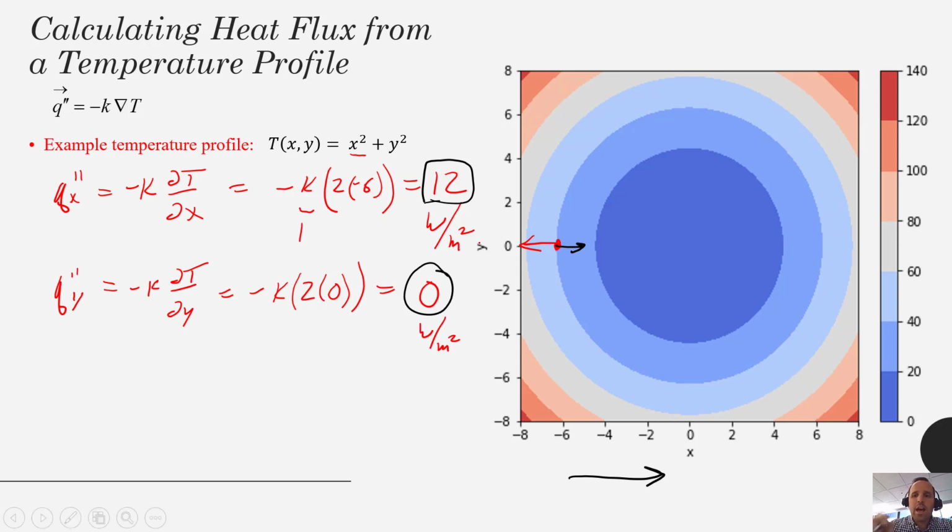We've assumed that nothing is happening in the z direction, so the z direction would be coming toward you out of the screen or going into the screen. We're just assuming that temperature doesn't change at all in the z direction. So our derivative of temperature with respect to z would just be 0, and we just neglect it. There's no heat flowing because the temperature doesn't change. There's no driving force for heat transfer in the z direction. This is a hypothetical example, but often we'll make those types of assumptions to make the math easier, and because we're engineers, we want to use good data and solve problems where we can have some kind of actionable step to take from our analysis.